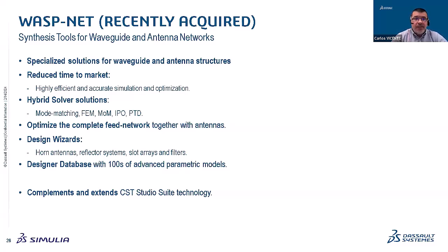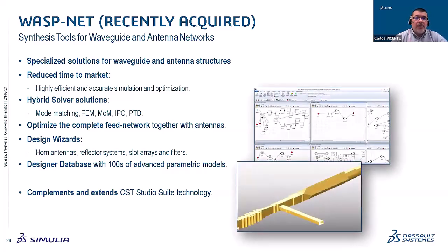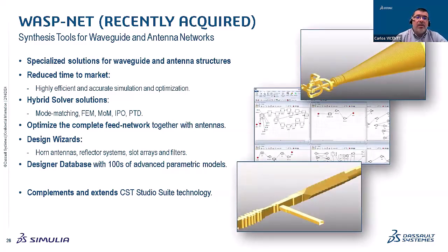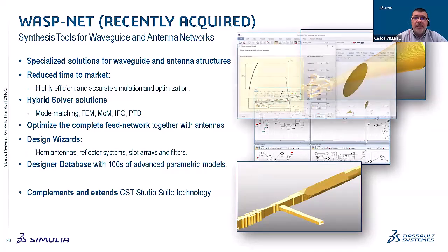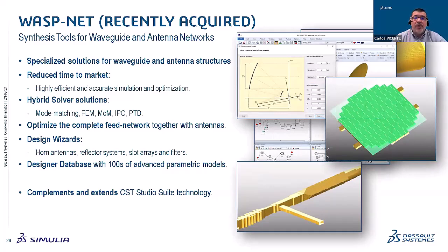So it uses different methods. It is based on mode matching, but again, it's also using hybrid methods like finite elements, method of moments, iterative physical optics, or physical theory of diffraction. And you can really optimize the complete feed network together with antennas. Very interestingly, it has very nice design wizards for antennas, especially, okay, where you can really design reflectors or slot arrays, okay, or horn antennas.